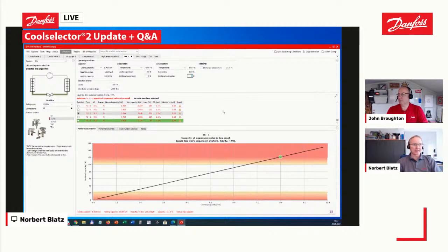If you come lower than that, it requires special evaporator design with inner fins at the inlet and so on to ensure that it will still work. So it's not that much a question of the valve as such, but what comes out of the valve and how can the system then handle that? Is the evaporator able to evaporate this? You will get a delay of evaporation of the liquid and so on. So there are many general aspects.